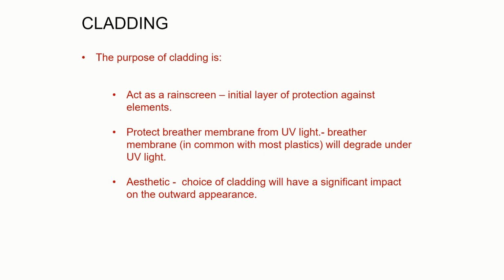from hitting it. It also needs to protect the breather membrane behind, and in the breather membrane lecture I touched upon the fact that if it's left exposed for any extended period of time, the UV light, the ultraviolet light within sunlight can degrade it, because it's made of plastic, and a lot of plastics will degrade in UV light. So we need something there that provides shade and cover for the breather membrane.